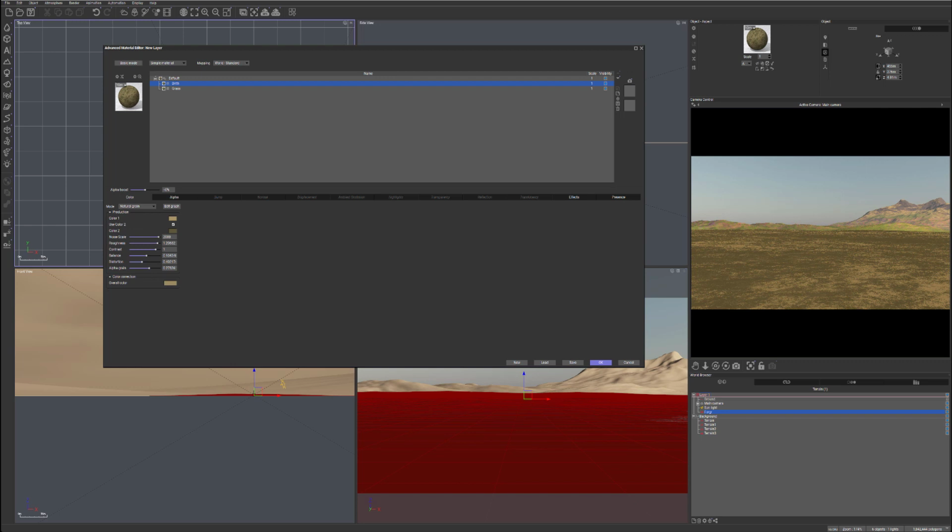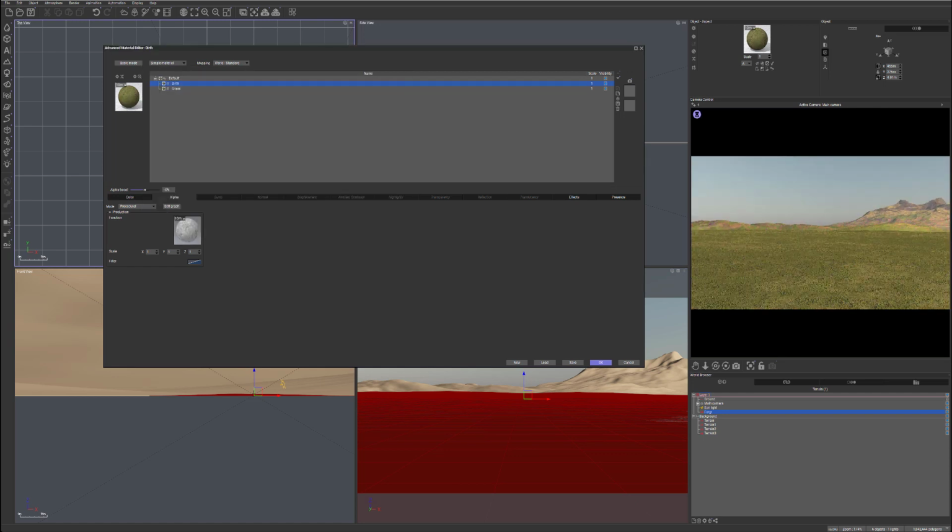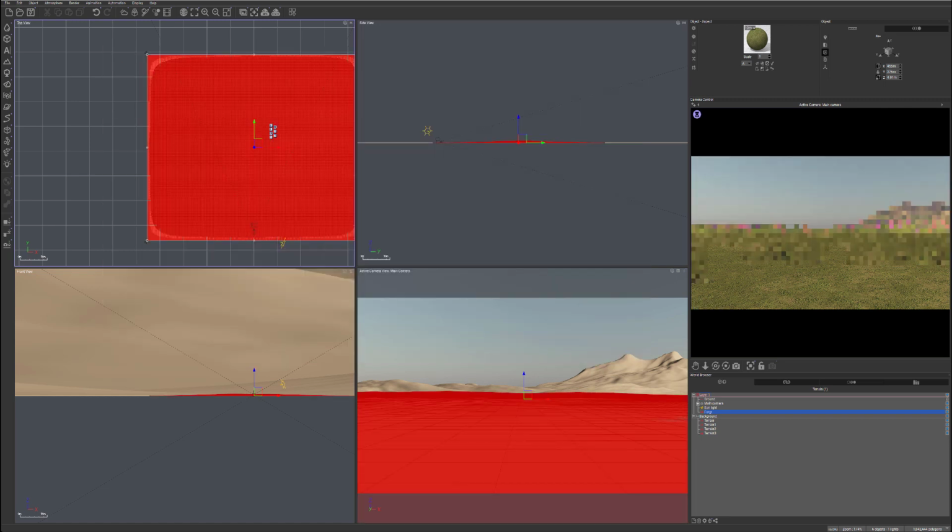One thing you notice right here, it is covered everywhere, so we want to go in alpha, go in the procedural alpha, and just apply it again in some areas. The nice thing is, if you notice, our bump map does not apply everywhere, and the reason is, if we look right here, you can see it has it add replace. So if we add, it's much stronger as add everywhere. And if we're going on replace, because we don't have any bump map in those areas with alpha apply, it will create this nicer look, kind of flatten. I think this way will help us to create almost a look like teeny tiny pieces of grass there. Let's click OK right now.